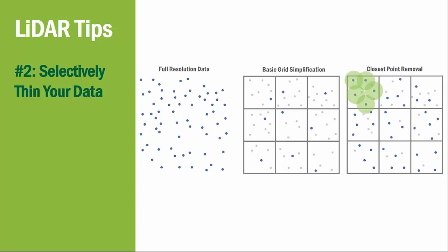Neighboring points within the cell that fall in the radius are removed. This method is considerably slower than the basic grid, and in this case, I recommend setting a radius smaller than the grid size. Both these methods result in a more accurate surface representation than we had back in version 7 on the importing option.